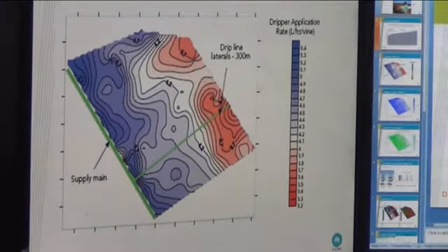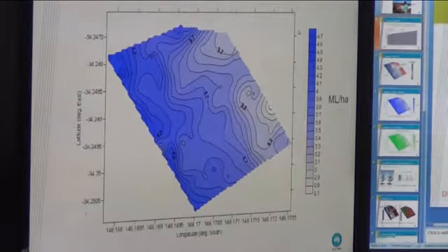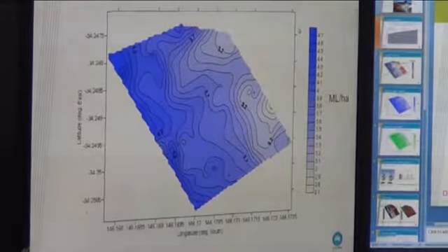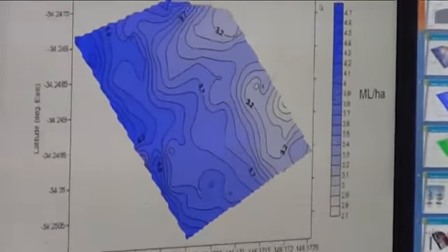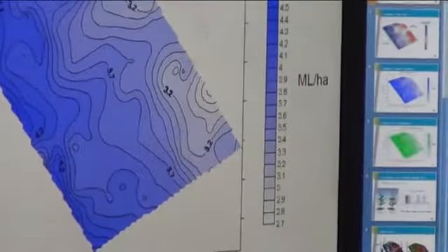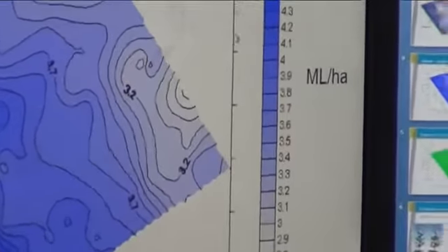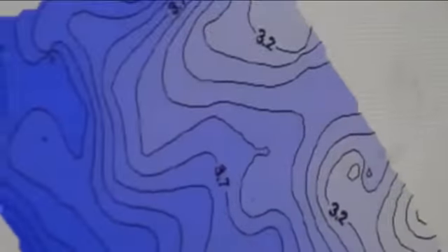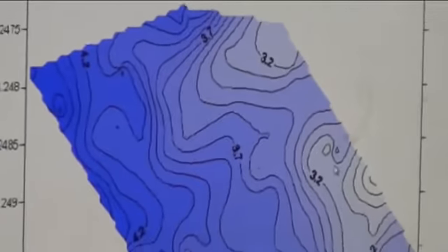But what does that actually mean for your irrigation crop? Well, I think one of the best ways to assess that is to actually have a look at a seasonal water use in terms of the amount applied. So if we look at total water use that's been applied through the irrigation system over the season, which will be generated within those reports if you put your seasonal runtime in minutes on there, you can see we actually get quite a variation over the block.